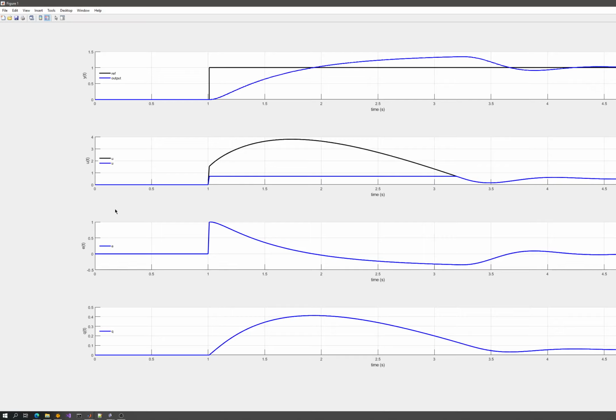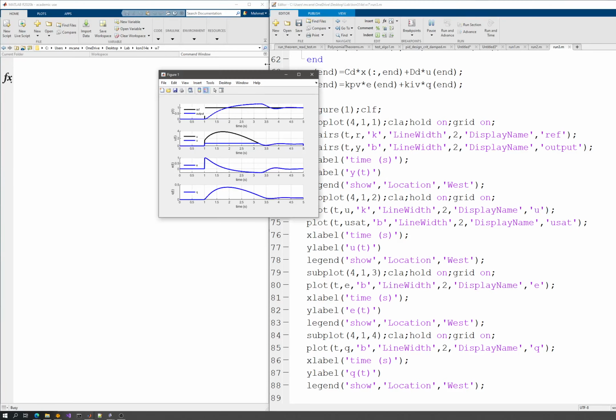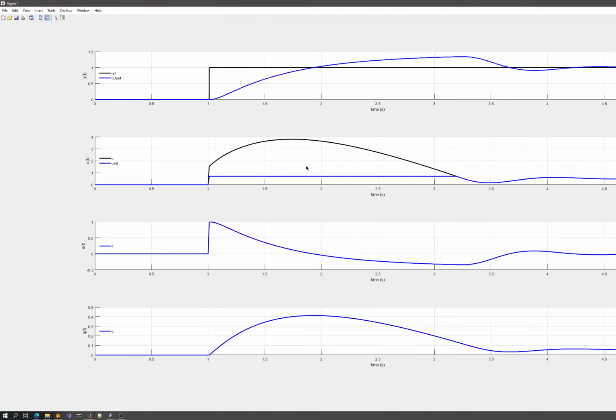Since I have used a step function that starts at a certain point, I can just assure myself now that I can see everything. Now I might also want to put in this U set here. And once that's done, I have this nice window where I can see what happens. Now, this is my response, and that was not the case. You can see that at a certain point, I reach the reference value, but my controller somehow has touched the limit, or it even starts with the limited value here,